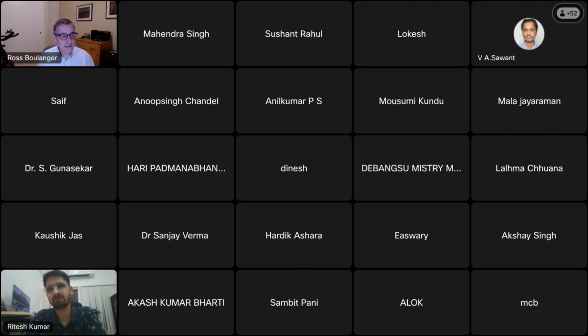And so part of it is the geology tells you a little bit about how wrong you could be. With a good engineering geologist, you can talk through it and say, here's my variogram for horizontal correlation at these two different distances. What's the scale of the river meander? How big was that river feature? How big might it have been in the past? Do we have any geologic constraints? And then you might decide that, I don't really know this number.